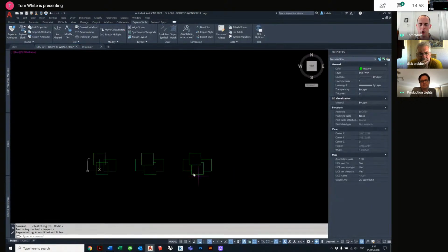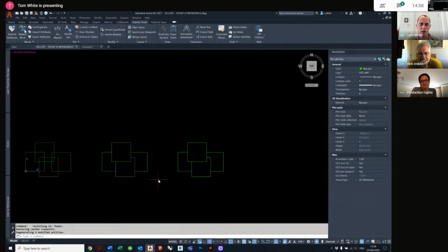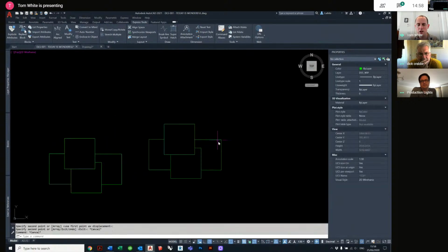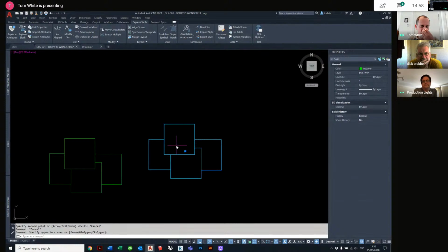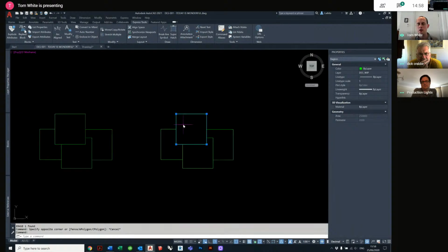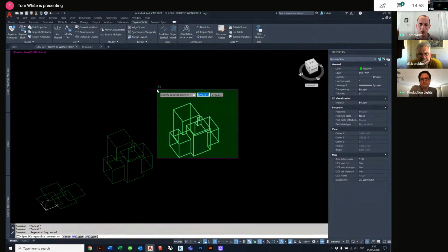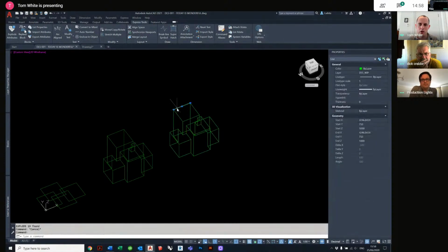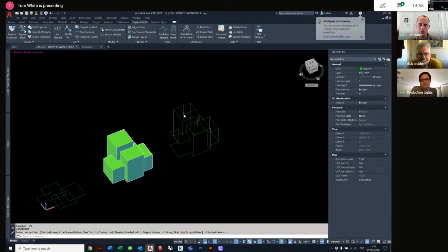Okay, so what I was trying to skip the process slightly. What I did here is I did a 3D solid, and the reason we know it's a 3D solid is because it's a closed polyline. You extrude it to a measurement, and then in this circumstance, I unioned four elements together. Those four elements are deemed as one 3D solid. I pulled it to one side. I used the explode command once to make it a region, and I thought I was going to tell a different story, but I'm going to temporarily explode it twice. So am I going to get anything? It's not ideal.